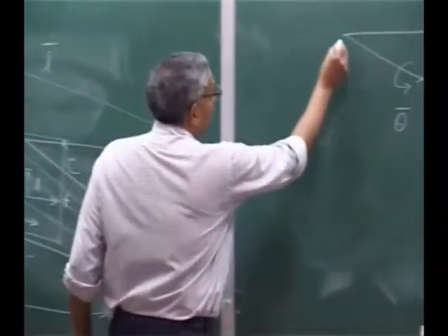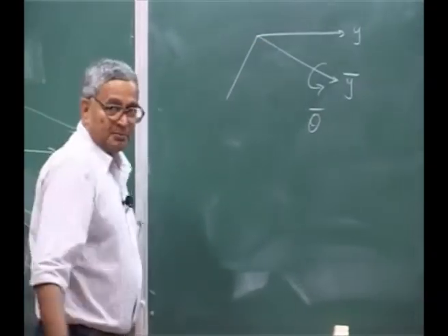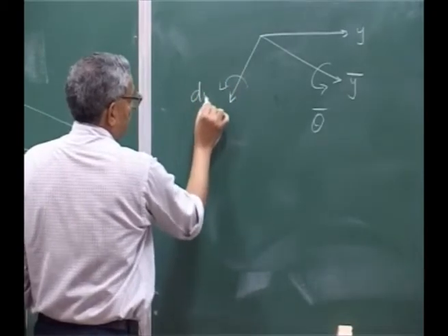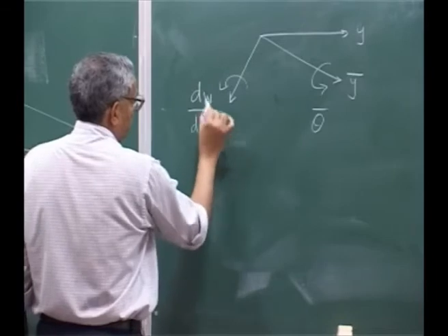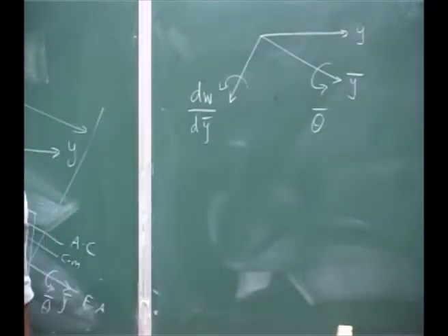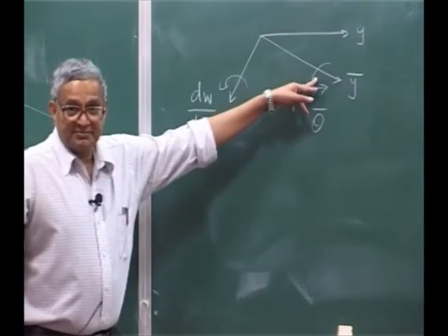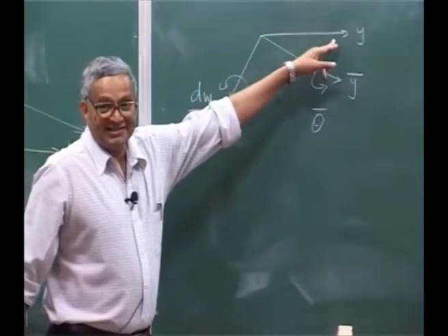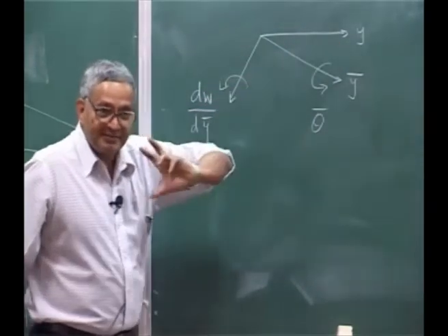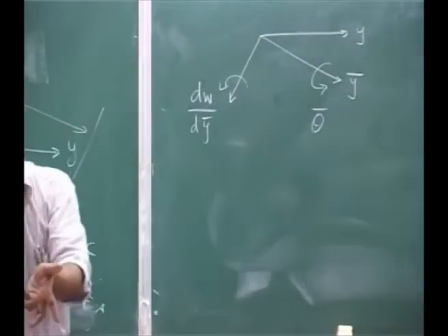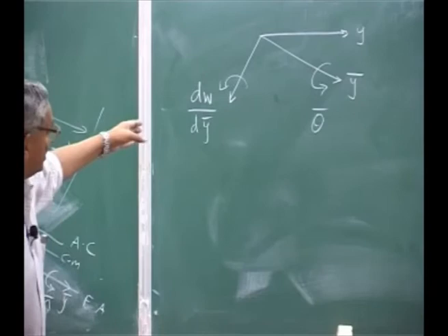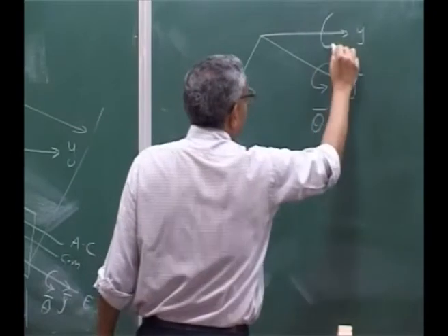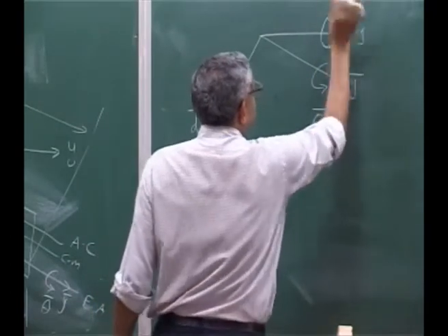Okay, so I am having a bending twist which is perpendicular to y bar axis. I want to know what is the change in angle along y axis. That is my elastic, you can say, change in angle of attack due to these two deformations. So that will be along y, I call this as theta.